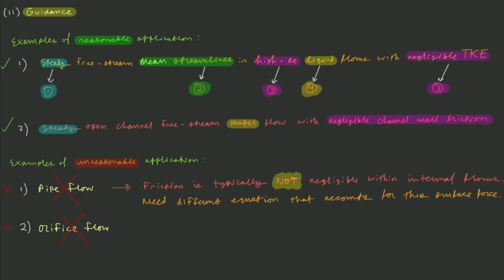Now, if you're in the realm of possibility and you're looking for an accurate model of how much flow you actually get through the orifice, Bernoulli's equation is probably not going to get you there. You're going to need something else like the fluid energy equation or CFD or something to that effect. Now, with all that being said, the next step is we're going to go into some example problems that teach us how to use Bernoulli's equation and the situations in which Bernoulli's equation is appropriate.